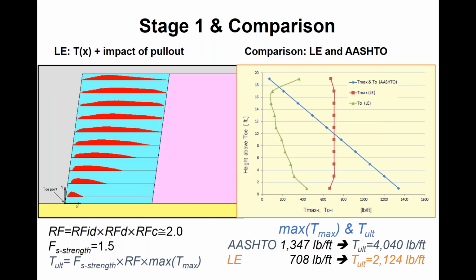But as opposed to finding just a factor of safety for a given reinforcement strength and doing a trial and error process of changing your reinforcement strength till everything meets a factor of safety of 1.3, what we do is we determine, given the full soil strength being used, like an active wedge, if you will, for thousands of surfaces, what reinforcement load is required to maintain that limit state. So that gives us that baseline solution, which is basically a distribution of tensions for each layer of reinforcement.